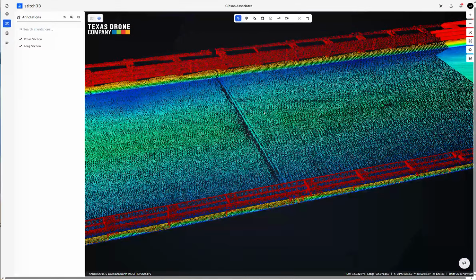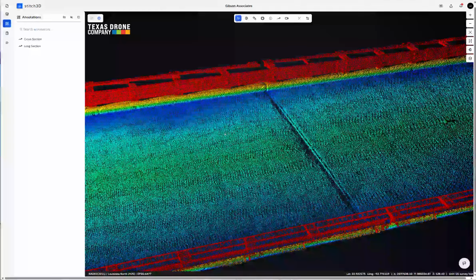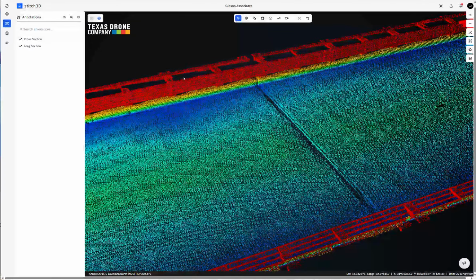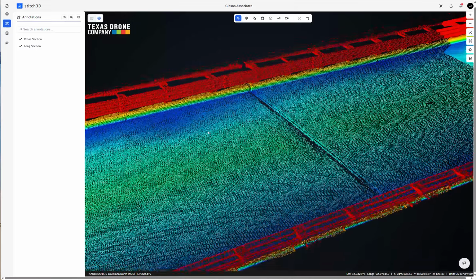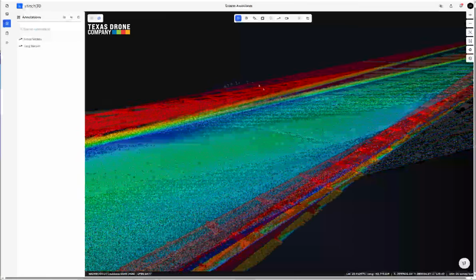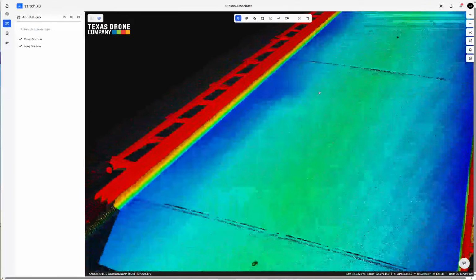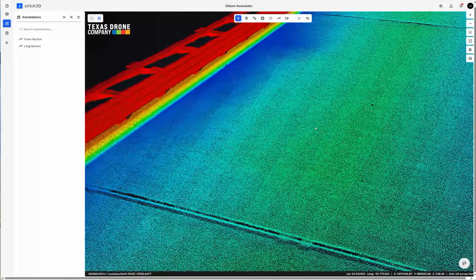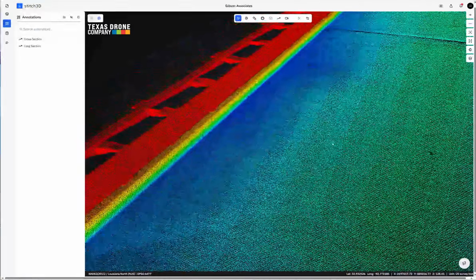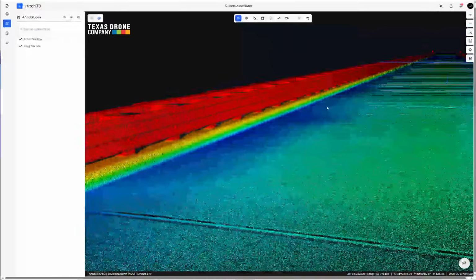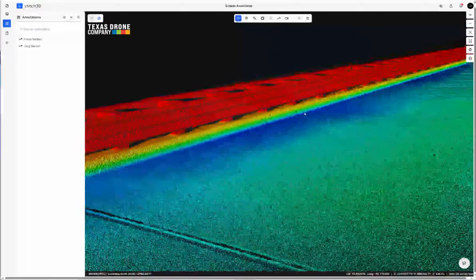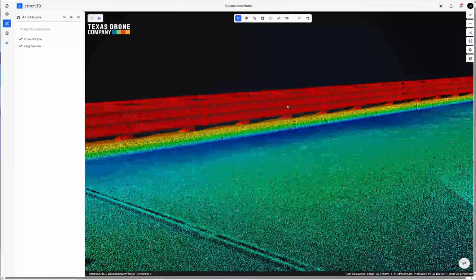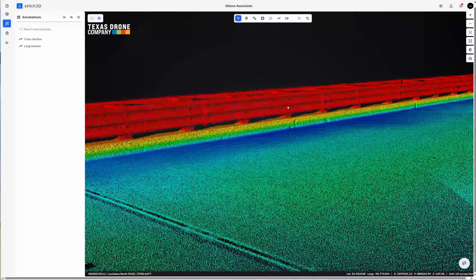So with the terrestrial, some things to note, okay? You see this kind of very sharp line there, and that can help you to determine exactly where the scanner was positioned, because that's shadowing. It is as if this was shining a laser and just rotating around, and so this is about where the laser would have been positioned.